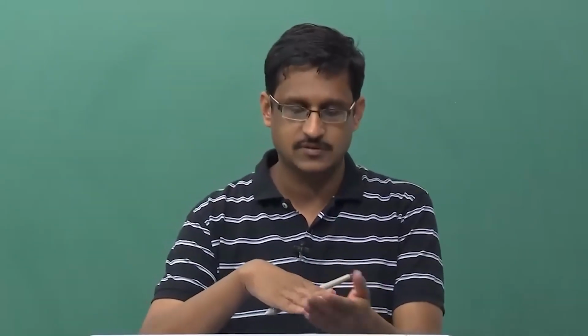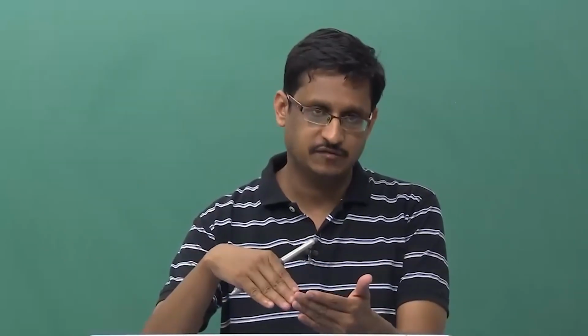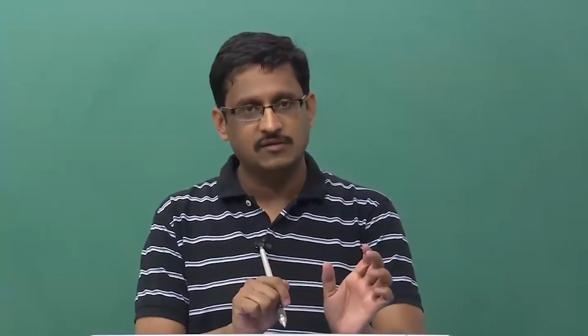LED stands for light emitting diode, and something that we are going to study later in this part of the course. Okay. But in general, I will not be able to take light from a bulb, or from a tube light, the conventional bulb and tube light, and then modulate its property and launch it into the fiber. If I were to do that in a standard communication fiber, if you recall, the light from a tube light or from some other light source that is visible to your naked eye usually covers the spectral range from 400 to about 700 or 600 nanometers, right. So, 400 to 700 nanometer, let us say.